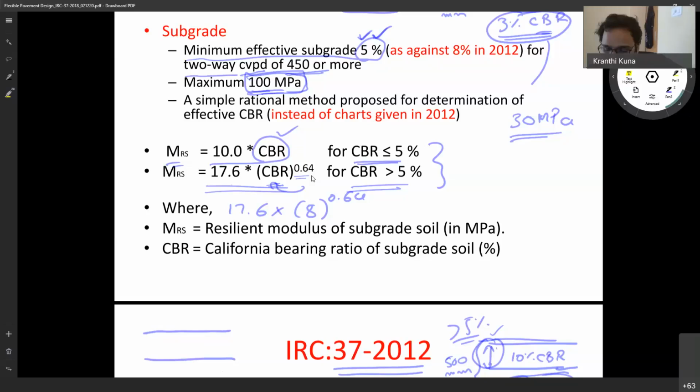No, earlier it was thought that unless you have an 8% CBR, if you are having lower CBR, there will be more deformation in subgrade. But now because we are putting some more material, this is not based on any performance data or anything, but it is more of a feedback that has come from the industry. Okay.